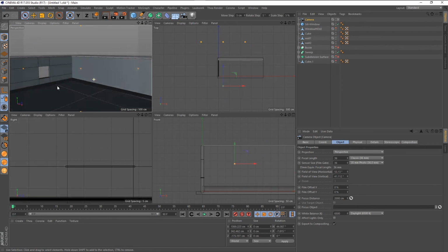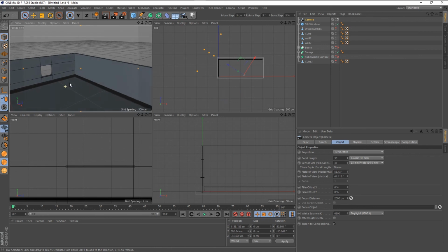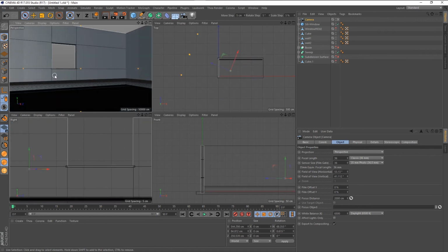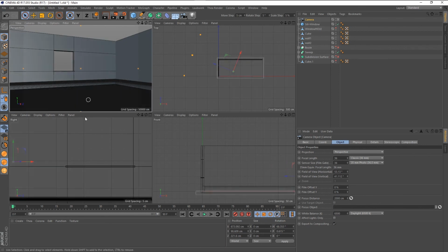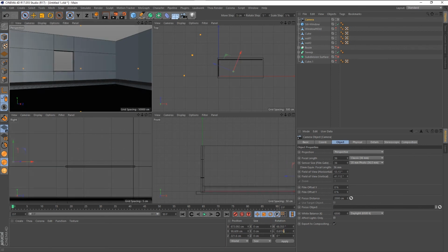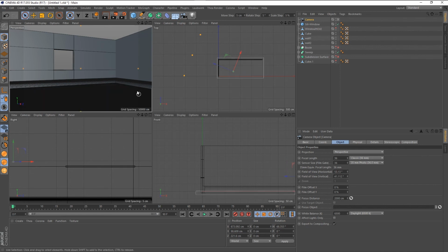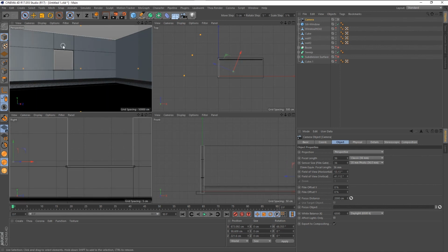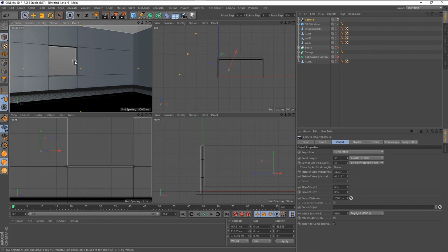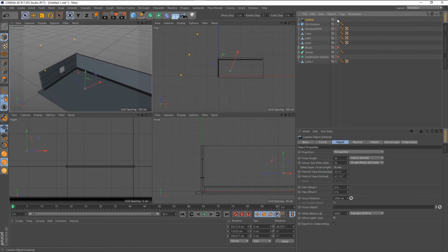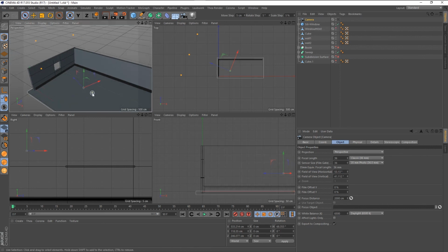And if I rotate this, it'll move my camera accordingly. Now let's say I have a good view and I want to set the pitch of the camera to 0. You always want the pitch to be 0 because you want your verticals straight. And there we go. And I can turn off this camera. Now that camera is fixed, and now I can continue working.